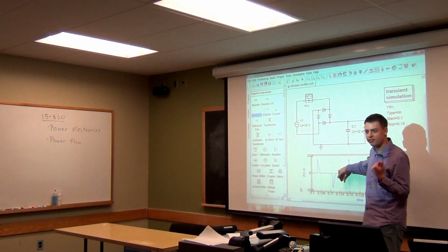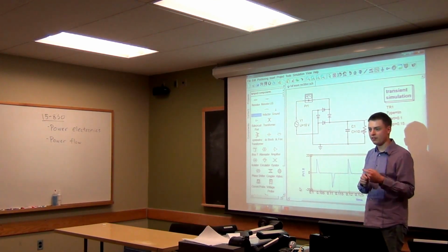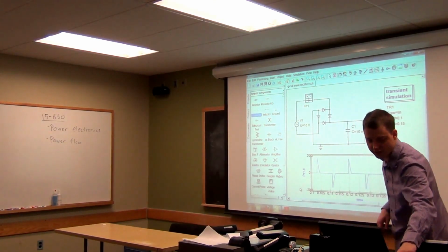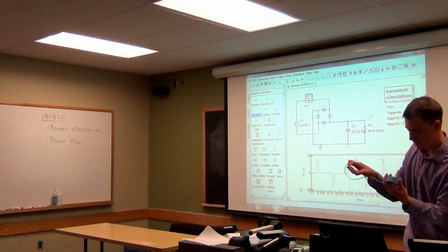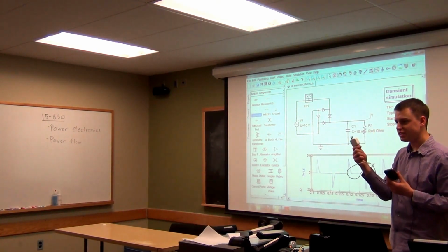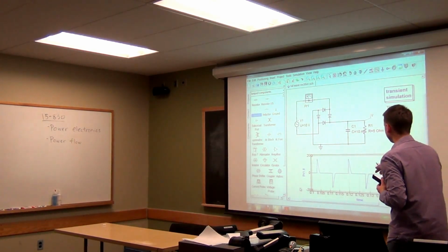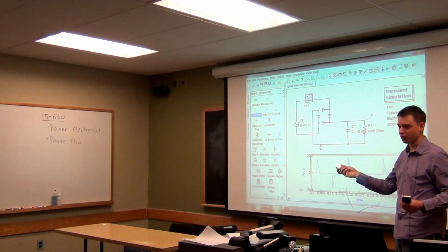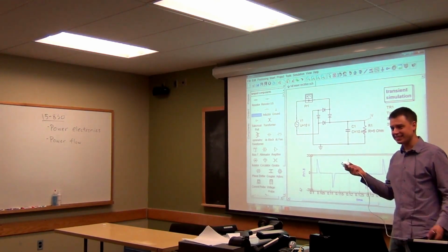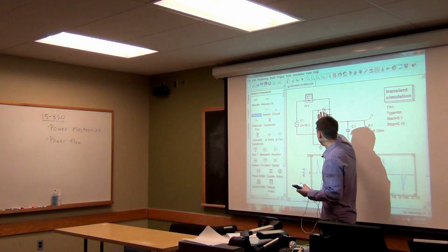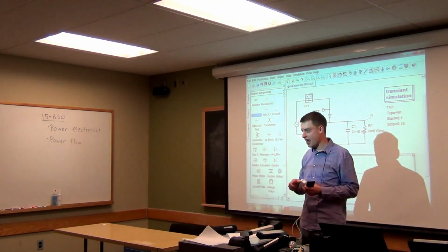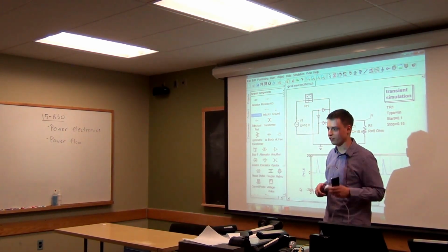And so this is exactly the kind of pattern you get from electronic devices that want a DC voltage source. Remember, my iPhone here takes DC voltage. This guy really outputs, I think, 5 volts DC. So this has this rectifier, and it also has a DC-DC converter which will step down the voltage to regulate it at 5 volts. But what it's doing is it has this rectifier in here and a capacitor that changes that AC signal, the voltage signal we're getting, to a DC signal this phone can actually use.